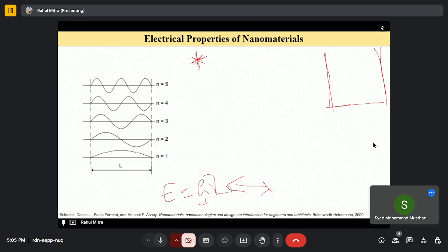Going back, the electron wavelengths that are multiple integers of thickness will only be allowed. All the other electron wavelengths will be absent. In other words, there is a reduction in the number of energy states available for electron conduction along the thickness direction. The electrons become trapped in what is called the potential well.